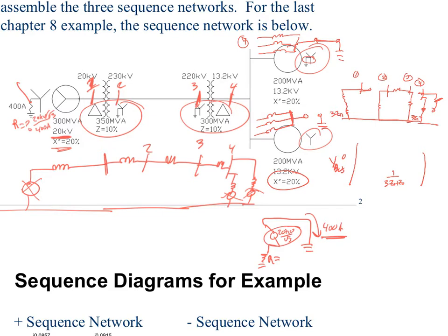So when we did our Y bus for our three-phase systems, we have to have current flowing through them to actually have an impact on the impedance. Can any zero sequence ever flow through that element? No. So that's the only one. I don't even include this one, right? Because it's not even connected to bus 3.